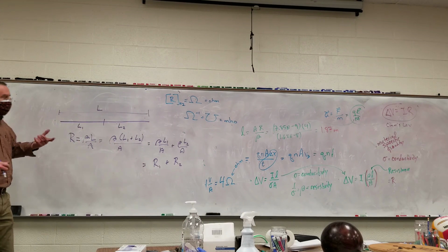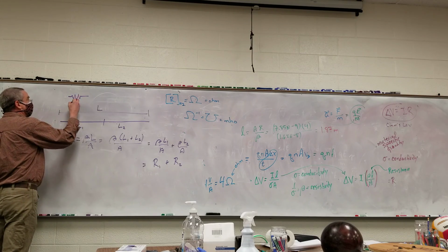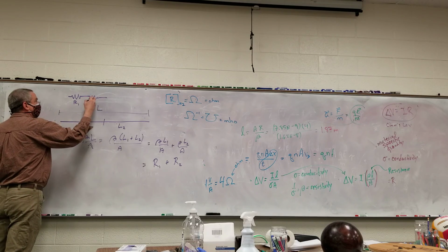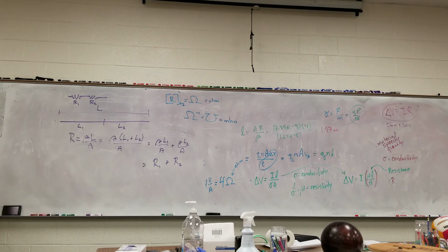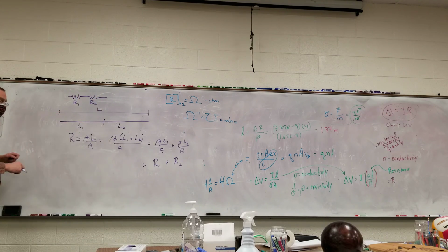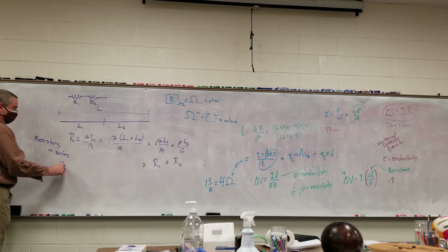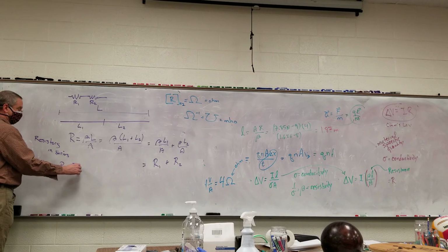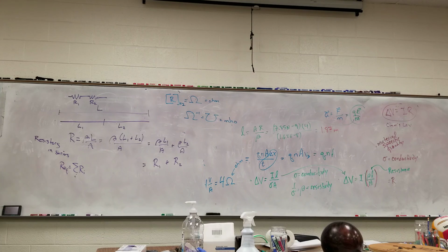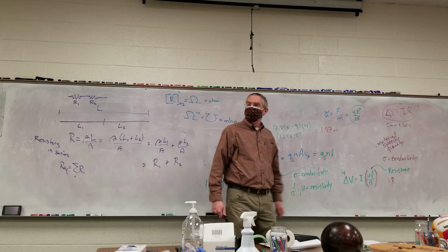So if I wrote this out in symbolic notation, if this is my resistor 1 here, I could just write it as resistor 1, and then resistor 2. In essence, for resistors in series, because any current flowing across one has to flow across the other one, there's no junction in between. So for resistors in series, the equivalent resistance is just the sum of however many I've got. R1 plus R2 plus R3 plus ad infinitum. Okay, so is it kind of like the opposite